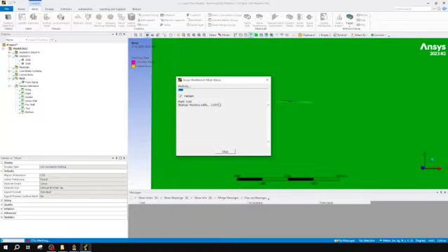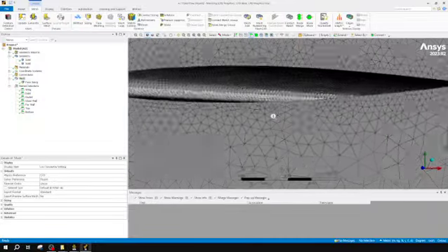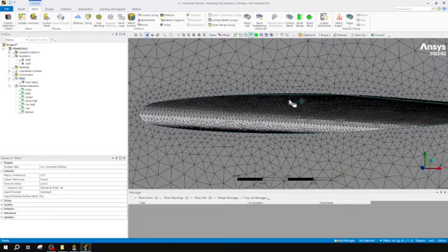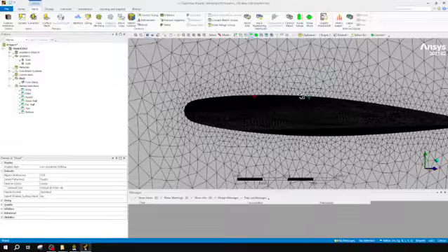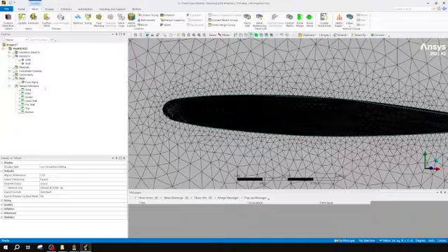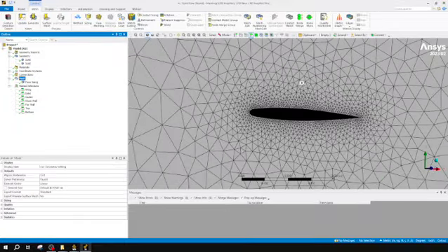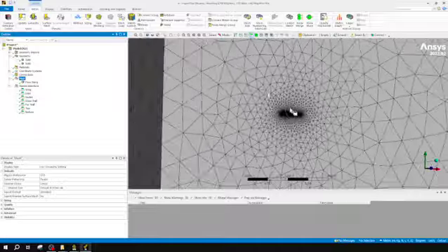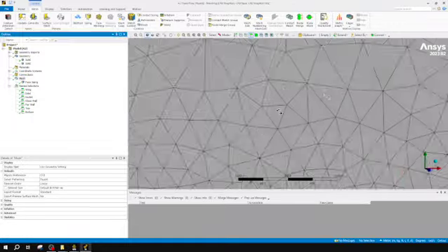So now that my mesh is finishing up, yeah, I think I added one too many zeros. You can zoom in and see your size. Again, for an actual simulation, I probably would go for something like 0.005, so about half the size you're currently seeing. But for this tutorial's purposes, that should be more than fine to give a nice gist of what you're doing.